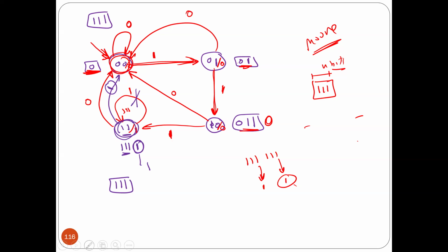Again, this is design. You need to think. So your question is why I don't move to here? Okay, if I move to here, what would happen? In this state, that means I have already received 1. I'm looking for 2. That means you are going to make an overlap for 1 bit. You got what I'm saying? So I need 2 more.